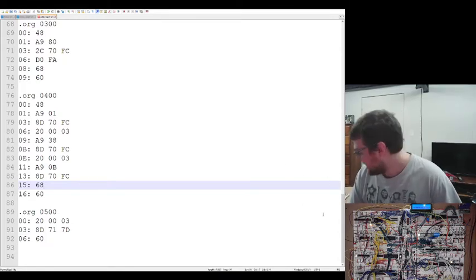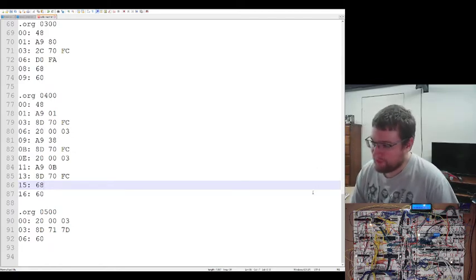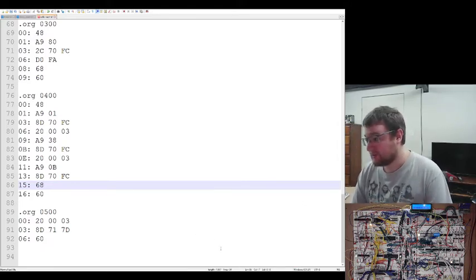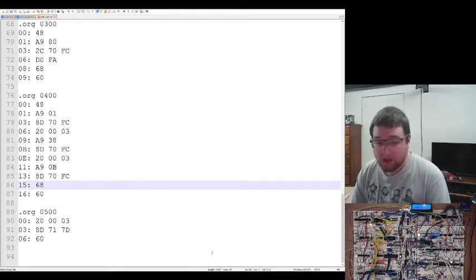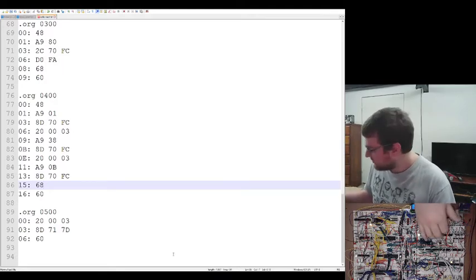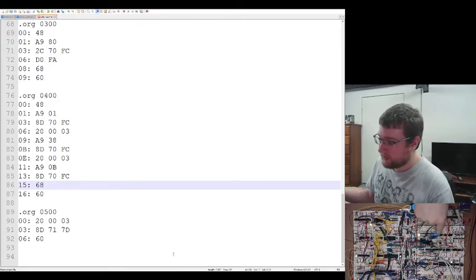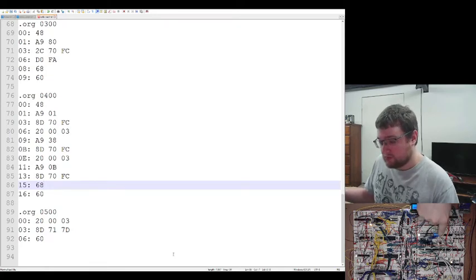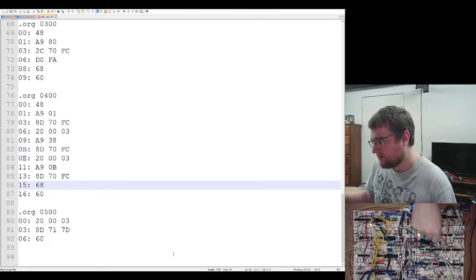So I do need to add some stuff for that. Because I was originally using the button, and now the button doesn't work, because it shorts things out. The button still needs to be used for writing, but I don't want the switches to come on when the button comes on. So I could make an active low OR gate, which is an AND gate with some diodes. That should work. Maybe? An active low OR gate. Yeah, I think so.